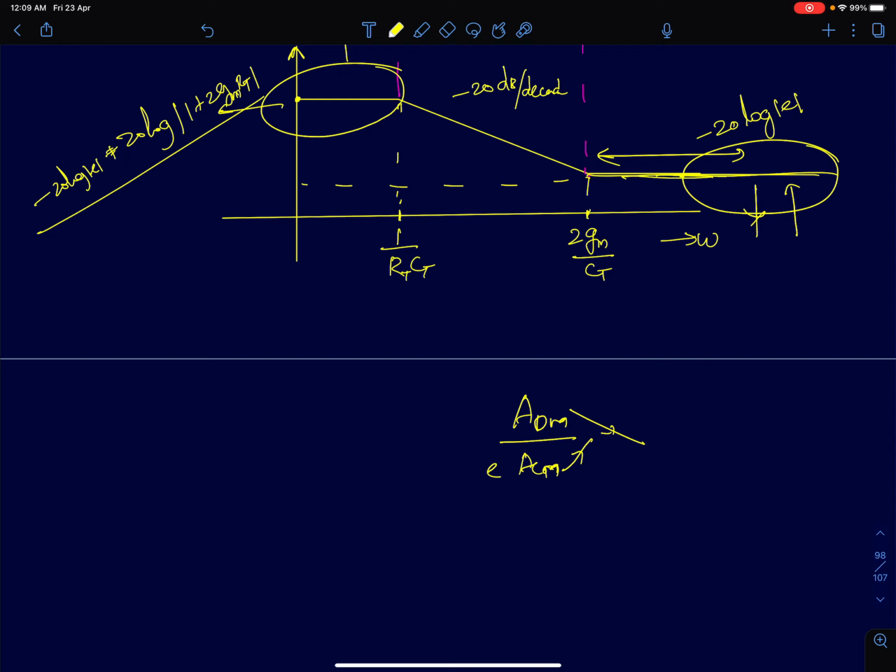And a decreased or low CMRR is definitely a bad thing, because for a differential amplifier, CMRR is a defining metric which tells us how good or how symmetric the differential amplifier is, how well it can reject common mode signals. The whole idea of going for differential amplifiers is that you are now operating differentially using differential signals, and therefore you should not, in theory, respond to common mode signals.